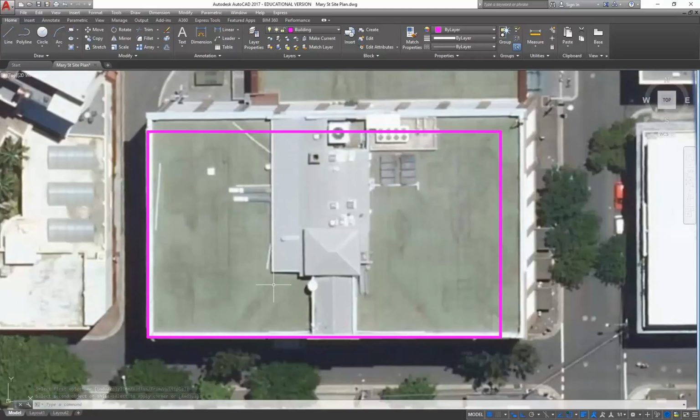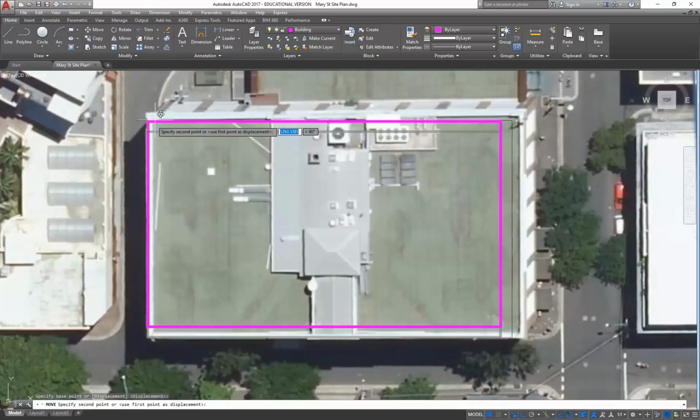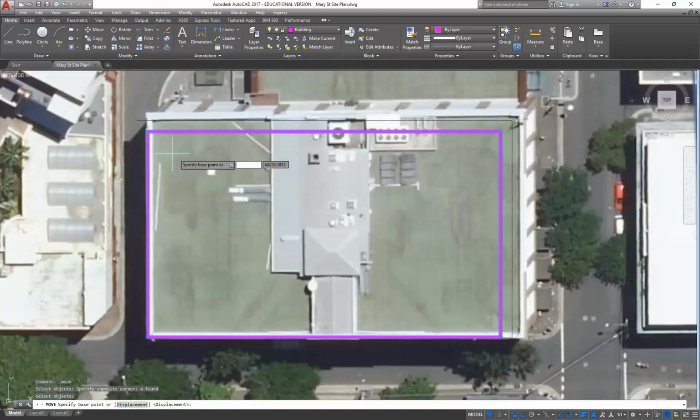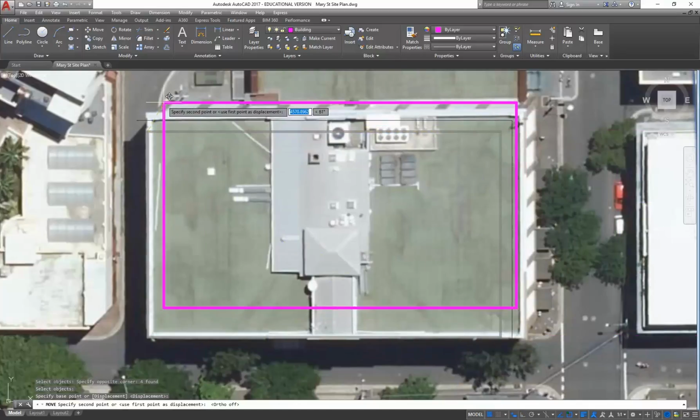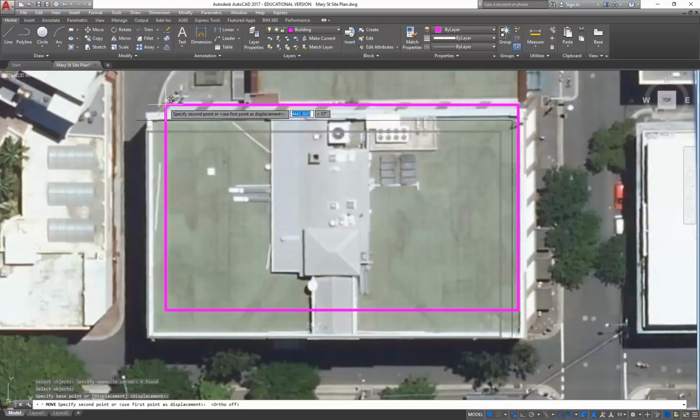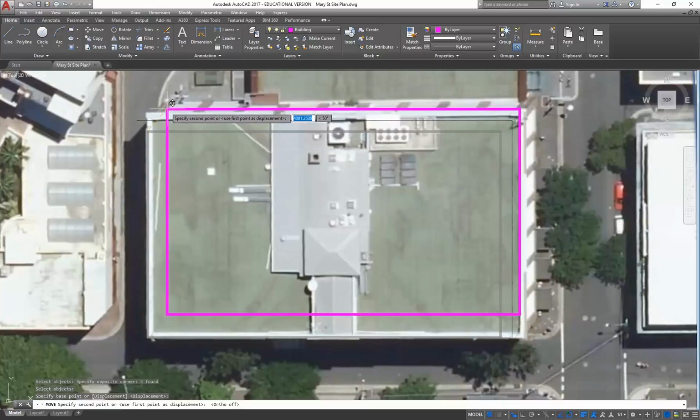Okay, so it's a fair bit smaller than the way it looks in the image. And also, remember that's a perspective, so we've got to maybe adjust that position as well. So I'm going to maybe select all the lines and then use move, and maybe move it to a location that's better. No, I'll turn ortho off. So I'm going to just place it maybe to line up with the bottom. Might work better. Again, it's never going to be perfect.